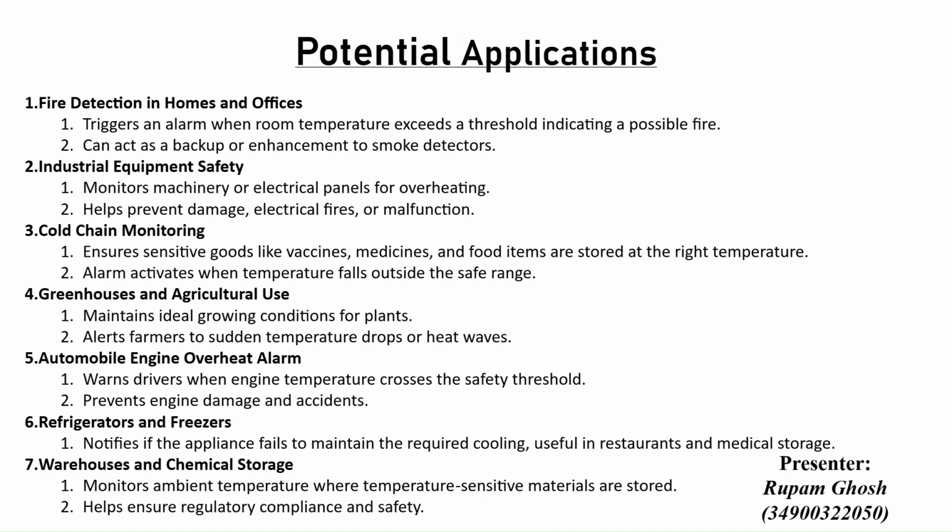In conclusion, our mini project demonstrated how a simple yet smart embedded system can contribute meaningfully to safety and automation in various domains. By integrating affordable components like the ESP32, DHT11 and a buzzer, we have created a real-time temperature monitoring system that is both efficient and easy to deploy. Its modular design also opens the door for future enhancements such as IoT connectivity and mobile notifications.